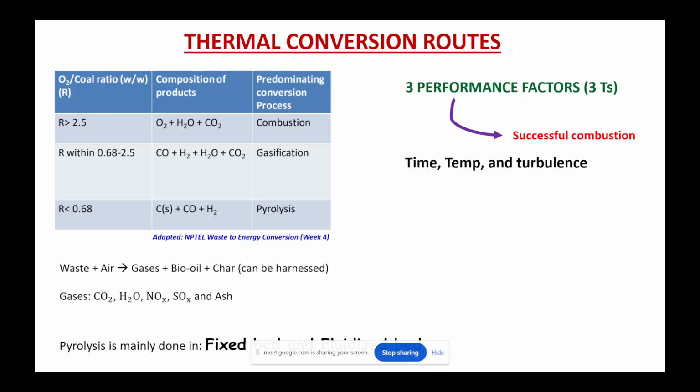So in this line today we will be discussing the concept of pyrolysis. As all of us are familiar by now, pyrolysis is a process wherein the oxygen is limited in amount. We do the combustion process, or you can say the burning process, in limited supply of oxygen, and that R value, the oxygen to biomass feed ratio, should be less than 0.68.